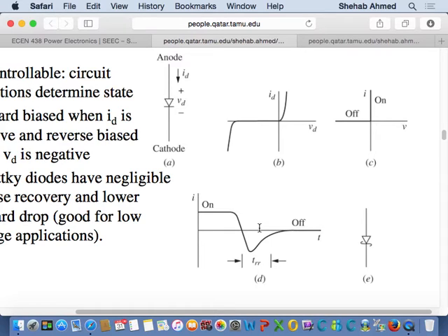This is time, right? If you want to increase the frequency of your pulses, and we will see why we want to increase that, if you want to increase the switching frequency of your pulses, then you don't want something to take up time that's not going to be useful. So this is taking up time that's not useful. So it will limit your switching frequency for sure. By how much? You need to do the calculation. You have to remove that from your ability to switch fast.